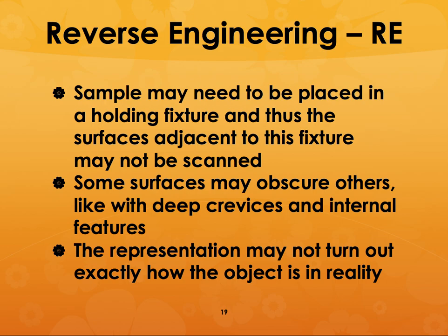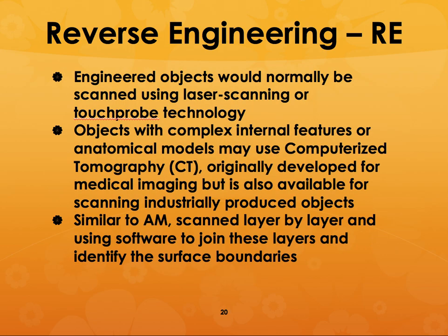And also you may have some surfaces that can prevent you from scanning other areas, like if you have deep holes and things like that, or you have internal features, you may not always see that in this scan, and it may not turn out exactly how the object is in reality. So you have to go back and manipulate this data.